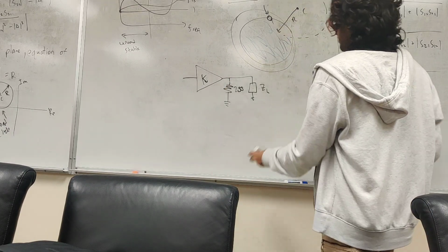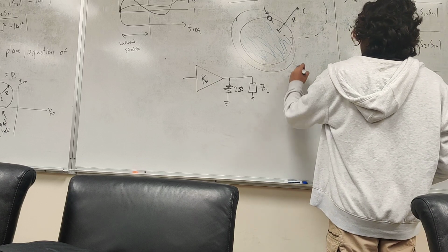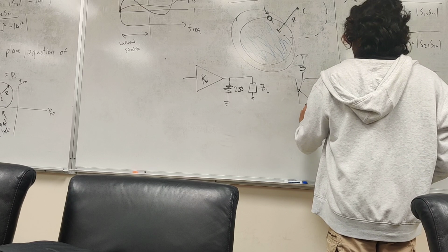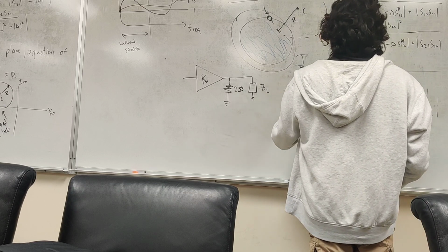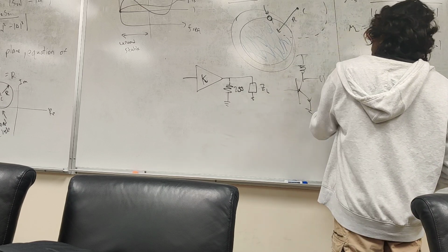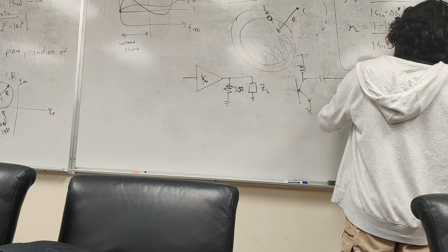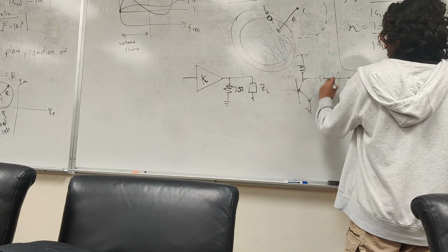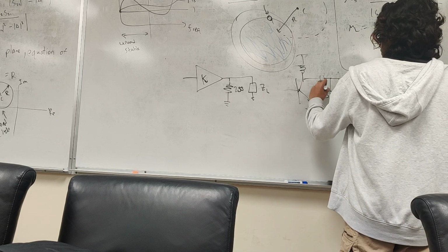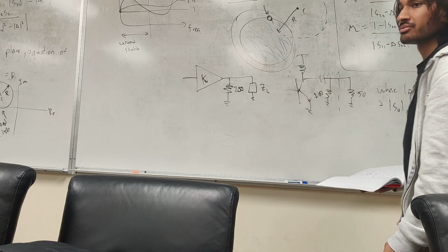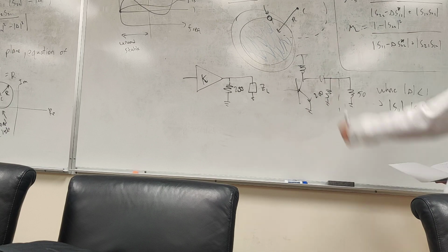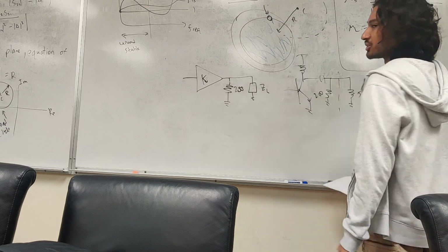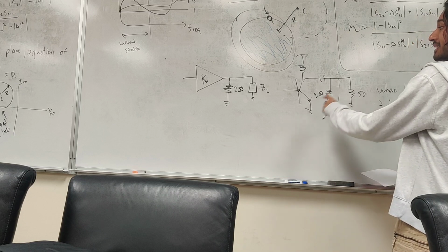So we go back to our amplifiers from before. Maybe we had something that looks like this. DC blocking cap, this is ground, you have the biasing network, blah, blah, blah, whatever, right? Now, this is like our load, our 50 ohms. Say that's the antenna. If this is the antenna, shove a 200 ohm resistor here. Now we're stable. We're good to go. So we did all that math just to come to, hey, you want less, put a 200 ohm resistor in there. That's the basis for all of this.